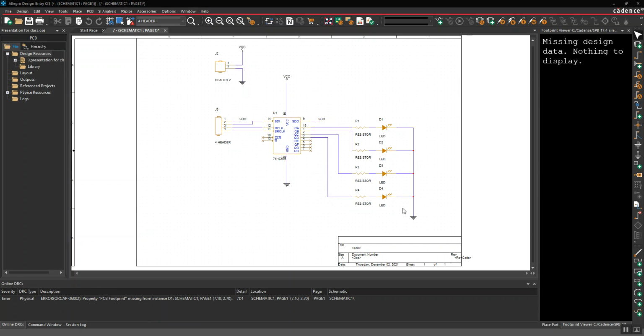Here we're going to talk a little bit about renaming components. For instance, you have a resistor, but you don't have a value. You never want to change the part that says R and the number. If you make these the same, you're going to have issues in your components because this is what identifies each different one. And the R represents the resistor, D is for diode, U is for IC, J is for jumper or headers. So you never change those. You change the label underneath.